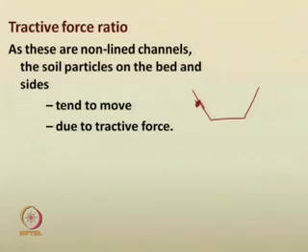If that component is sufficient, there is a tendency for this particle to roll down the side slope. And of course, if there is tractive force from the water in the channel, that will also cause the movement of this particle. So, the bed materials can move due to tractive force as well as the component of the gravity force of the particle that can cause sliding of the particle along the side slopes.